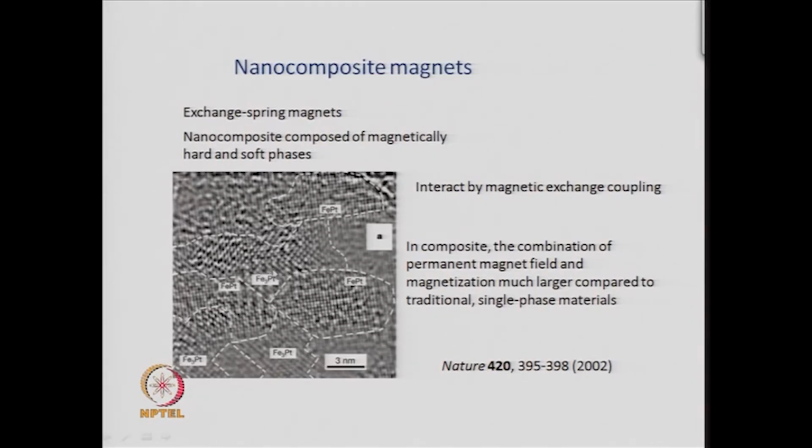The lines you are seeing here are called lattice fringes, and they tell you about the crystal structure, the difference in the planes, atomic planes in the material. So, from that we can identify that this is iron platinum, one from their lattice fringes, second by doing energy dispersive X-ray analysis on this part of the sample, you can find out that this is iron platinum 1:1, and this part we can find out that this is iron platinum 3:1 ratio, and they are two different types of materials.